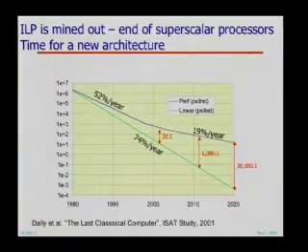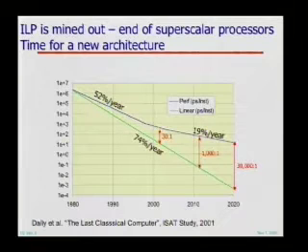The third component of that 52% a year remains with us, and that's faster devices. Devices are still getting faster, roughly 20% per year. But over this period from 1980 to 2000, because we also could make our pipelines deeper and wider with more instructions per clock, we were able, without changing any of our software, to turn Moore's Law's transistors into better processor performance and yield it on a single thread. The green line basically shows what you could get if you converted every additional transistor to performance linearly and took the 20% per year you're getting from faster devices as well.